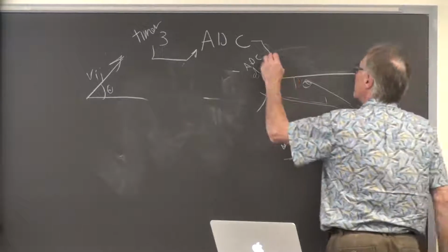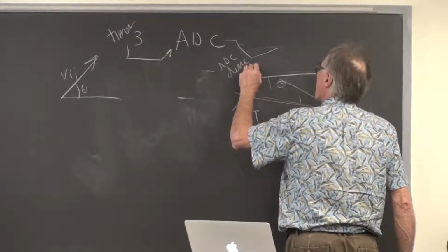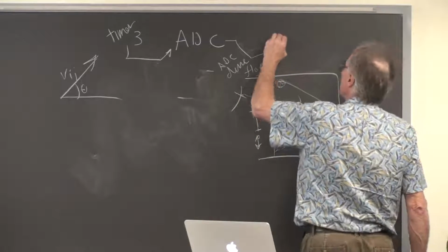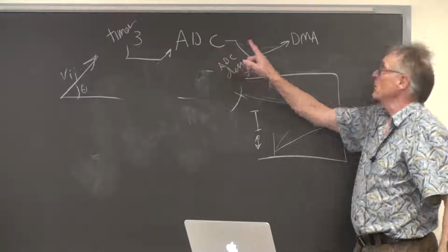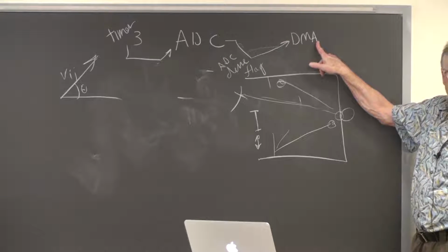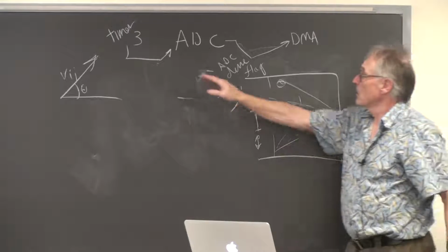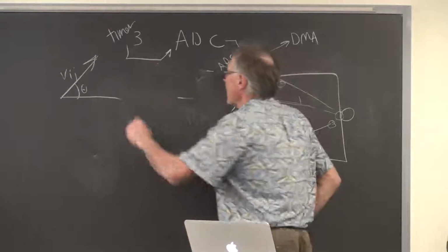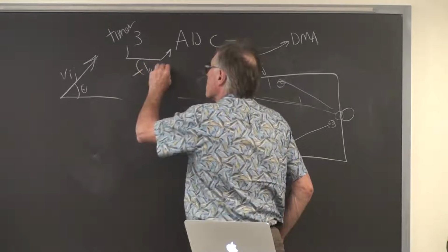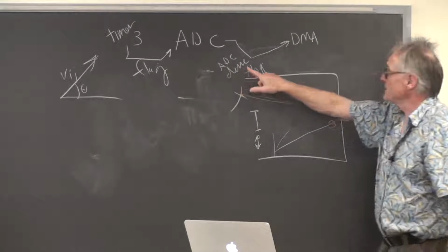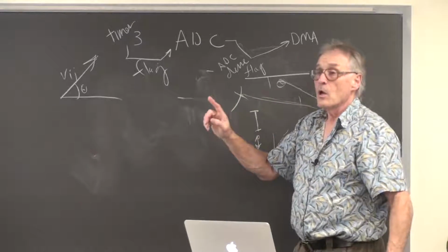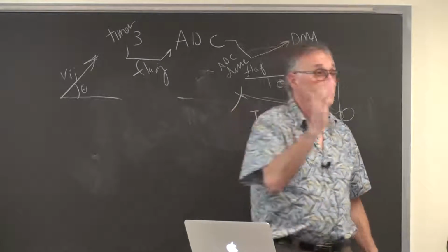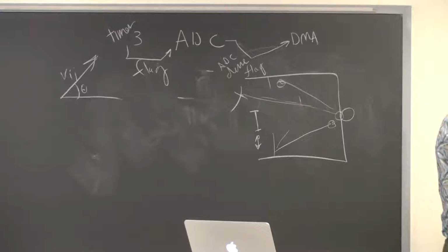The ADC done flag does not trigger an interrupt service routine, but rather a DMA burst to move the ADC value to memory. So the timer 3 flag is directly triggering the ADC. The ADC flag is directly triggering the DMA burst to memory. So data makes it from the ADC to memory at a regular interval as determined from the timer with no CPU cycles used.